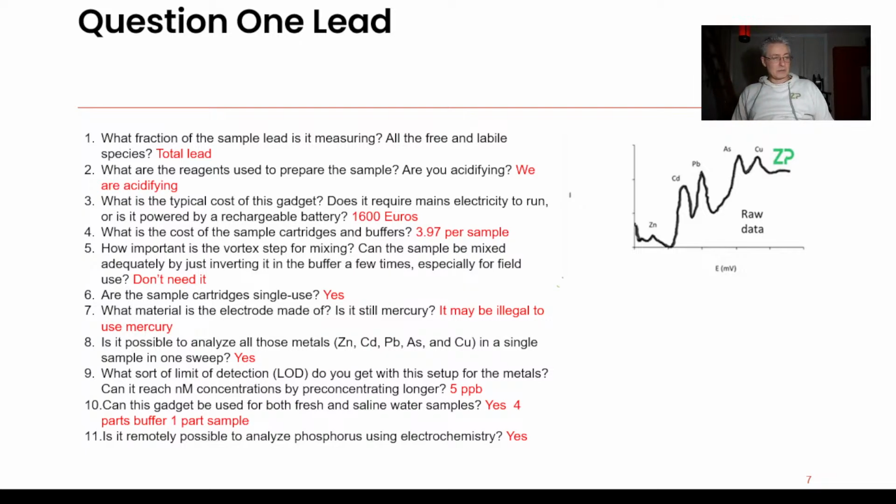So if I wanted to do phosphate in the field, I'd have to do a 2-part measurement. First part is essentially a single point calibration on the sensor, and the second part is add the sample. So we haven't brought phosphate to the platform for that particular reason, because it feels a bit harder for the end user, if I can put it that way.